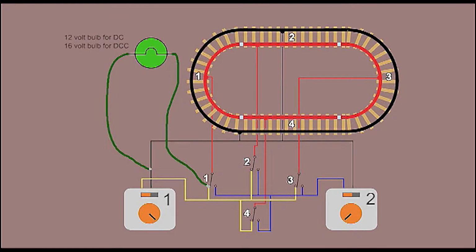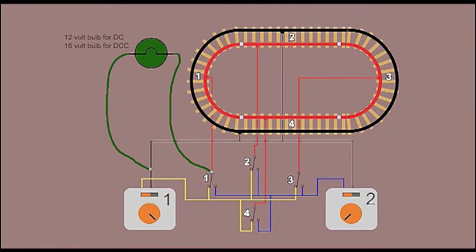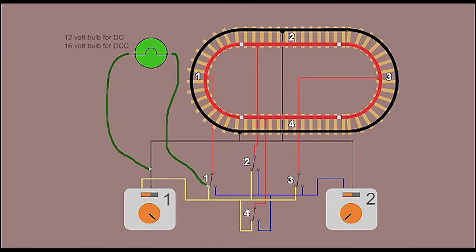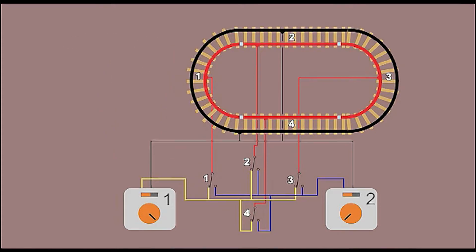So we've got our 12 volts there, we just don't have it on the other side of the switch. This tells us then there's something wrong with the switch. Either the wiring around the switch, something's possibly dropped off the switch, or the switch itself could be faulty. Check that out, replace the switch if necessary, and everything will be fine.